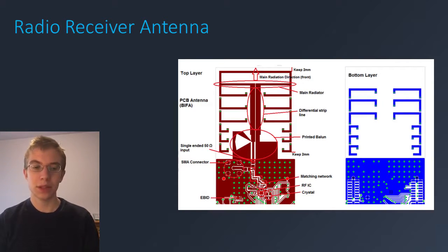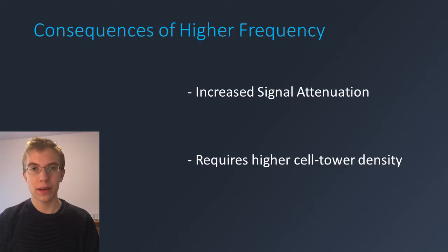Typically, the signals are transmitted in terms of ones and zeros, where a voltage threshold determines if a 1 or a 0 is registered. The downside to this sort of transmission is that a high frequency is required in order to deliver data at a fast enough speed. This high frequency of the radio wave means that the signals attenuate much faster compared to their lower frequency counterparts, and as such, reception in buildings, for example, degrades very rapidly.